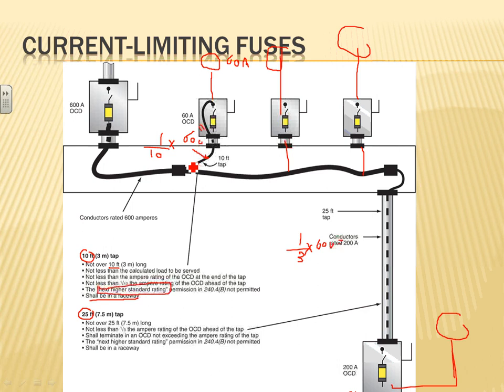I have a couple of rules related to taps that we cover when we do the class about transformers and transformer protection. Any comments about the taps? Any comments? What's the advantage of it? Cheaper equipment. Disadvantages: you don't have localization of all your overcurrent protection devices in one panel.